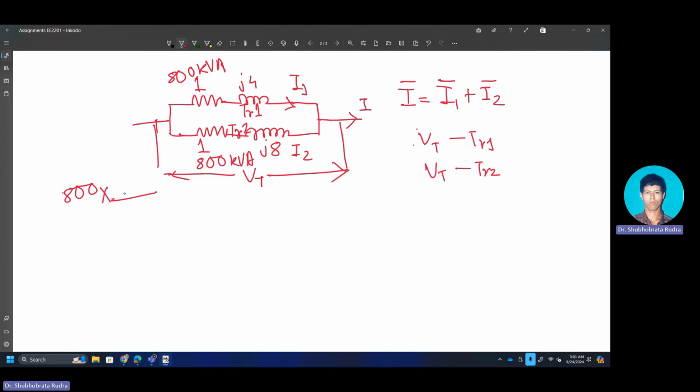you have to calculate the magnitude, that is √17 divided by √65. Sorry, not √5, here it will be √17 divided by √65. So this is the portion that will be transferred through this second transformer, right? So that you have to figure out, the amount of kVA that will be transferred through your second transformer.